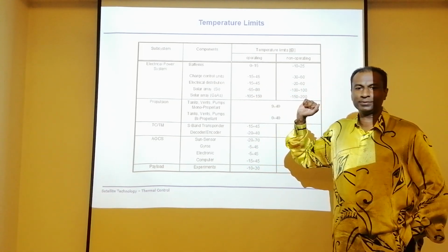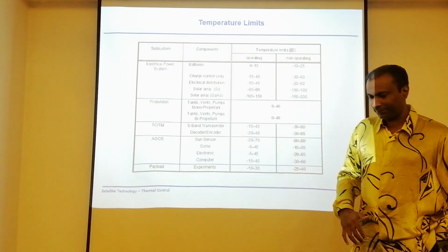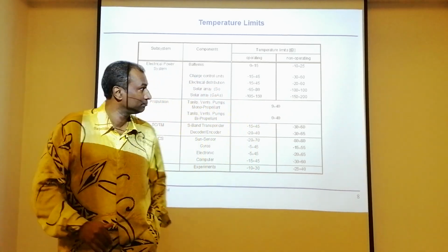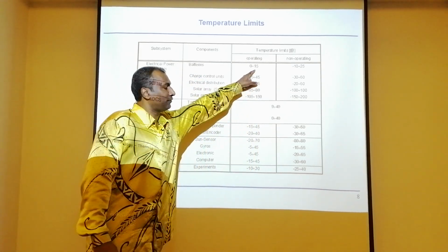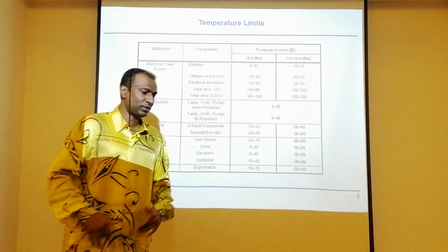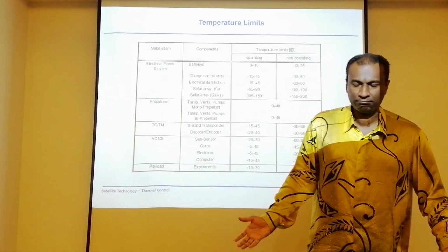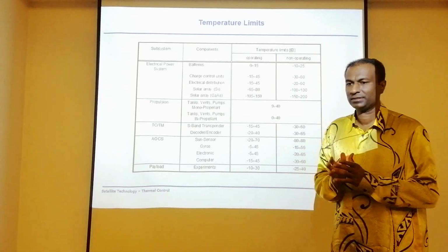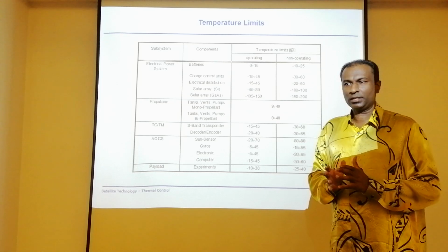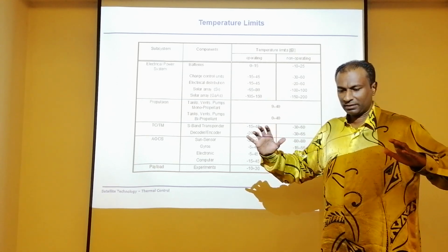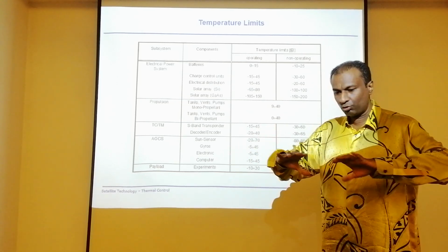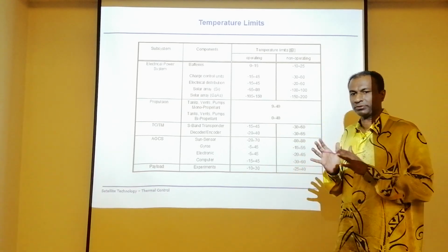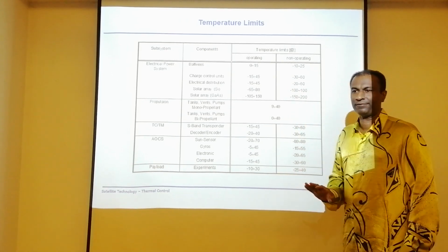subsystems. Okay? So it is not like you go from one compartment to another compartment and the temperature is 50 degrees, and from one compartment to another you need to maintain, let's say, 30 degrees. No, that will be too complex to do. What you should do is maintain the overall global temperature in the satellite around a mean of about 10 degrees, and all of them can survive.